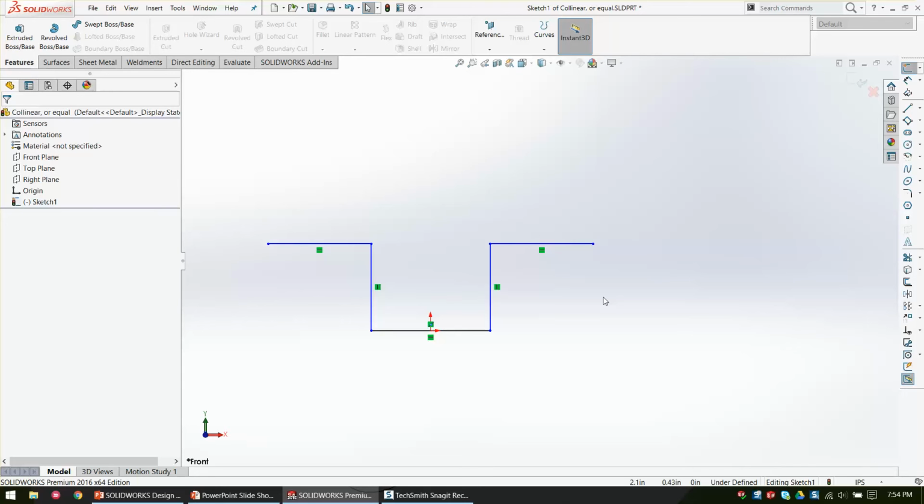When I go to start a plate, if I'm drawing a plate of steel for a machine, I don't go through 5 different questions in my head anymore. I pick the plane that it is in machine design, do a center point rectangle, grab my dimensions, do a mid-plane extrude, and I'm done. That's just the rule. I follow it, and it works really well.